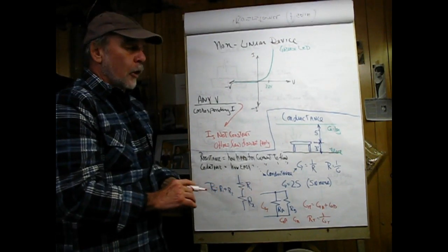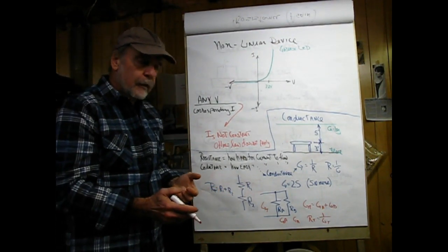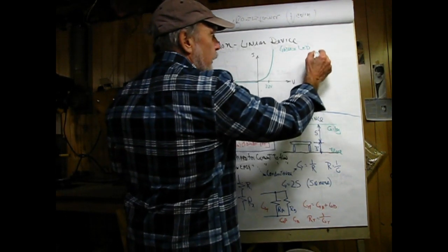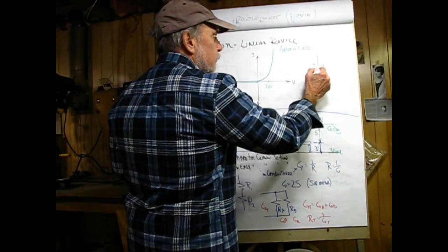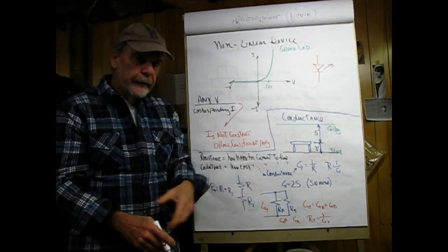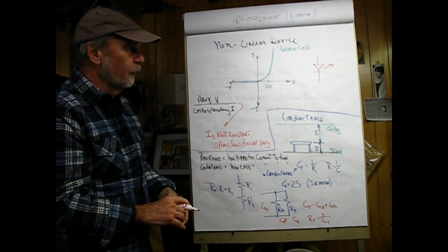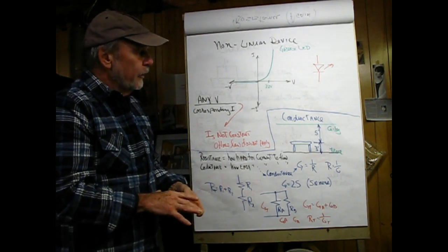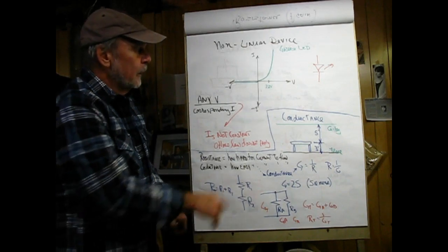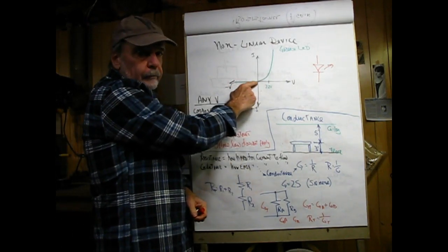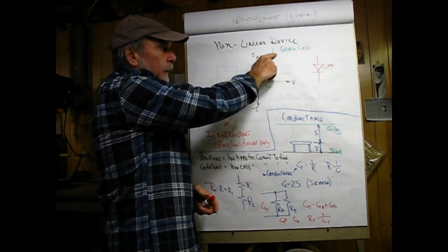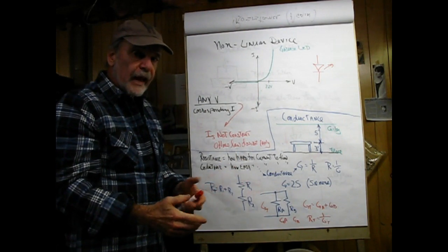So we talked about Ohm's law, and we said it's very linear. Let's talk about a device that isn't linear so we can contrast it. That would be a light-emitting diode, and the symbol for that would be this. There's a little arrow coming off of it, and that arrow indicates that it's emitting light. So that's the symbol for a light-emitting diode. And its characteristic curve, and again we're using the same coordinates that we used in the other problem, we see once we come off of zero here, 0 voltage equals 0 current, we start up a curve, and curve means it's nonlinear.